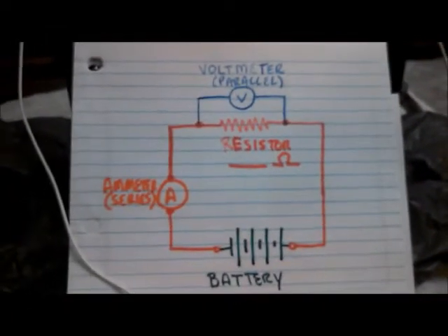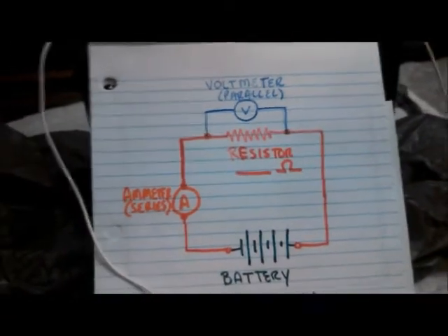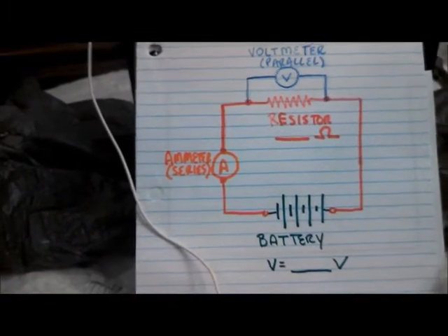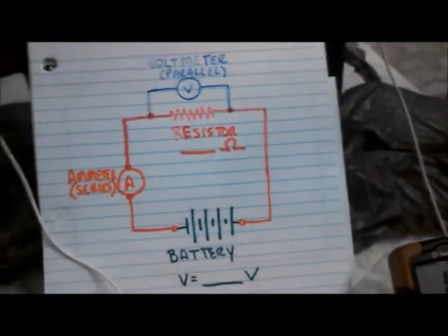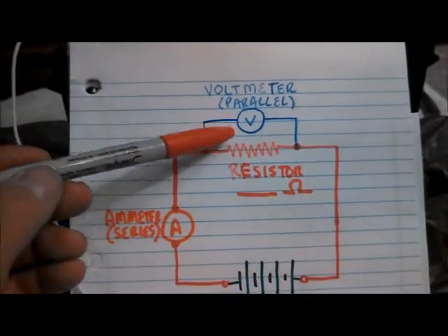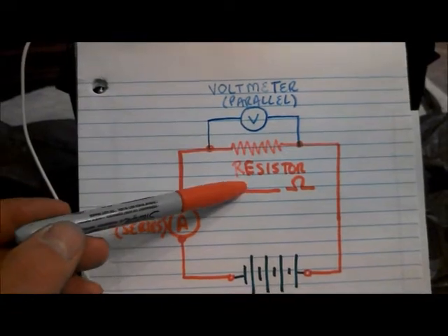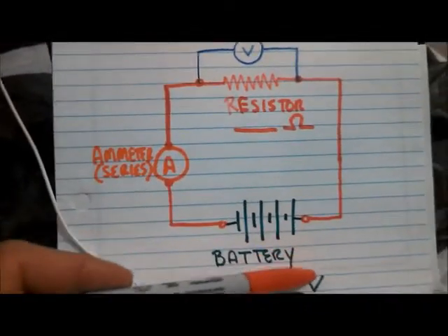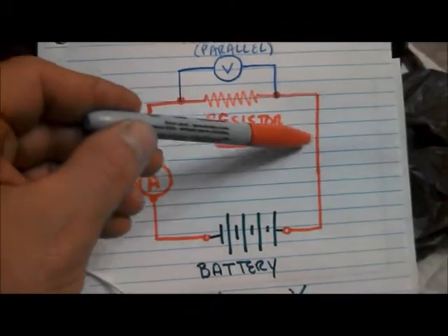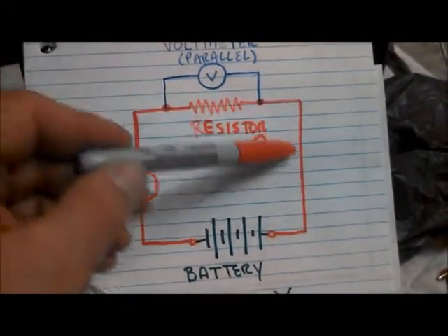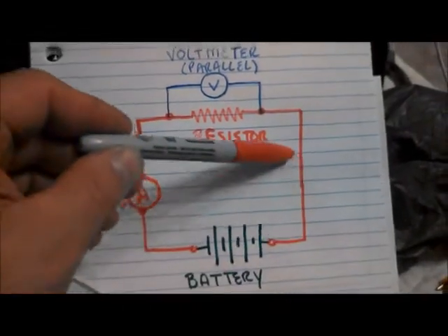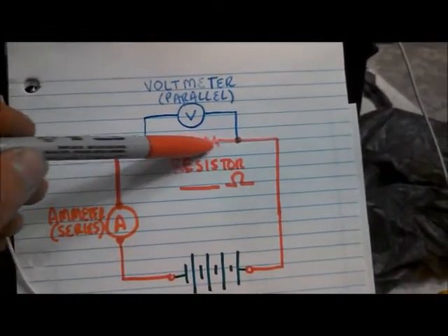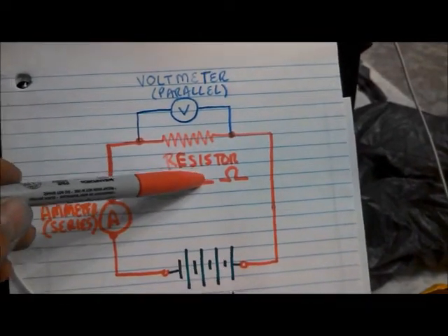So we're going to look at it as a schematic. What I've got in blue up at the top is a 12 volt reading that we're going to have here. The resistor that we'll put in here will be 553 ohms. That will not have changed. The battery down here will be 12.7, and the voltage up here will be not the 12.7 exactly, but the voltage drop, what's called the voltage drop across the resistor.